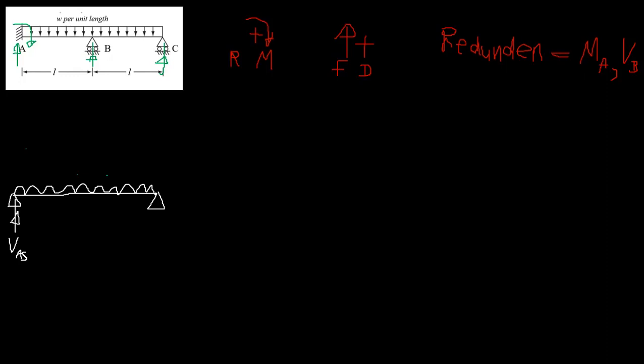We can solve for forces because the statical indeterminacy was 2. So that means two additional equations are needed. What we did is remove two forces. Then our equations are enough, right? So you can determine this. This is a determinate beam.